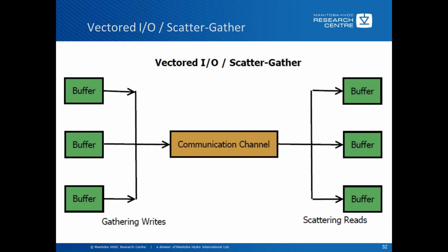So we'd run the 3 transmission lines into a single communication channel and then demultiplex it on the other side to the other process. This reduces the number of communication channels between the individual processes. So the idea is to improve the efficiency. And we use a classical scatter-gather technique for collecting and then demultiplexing on the other side.